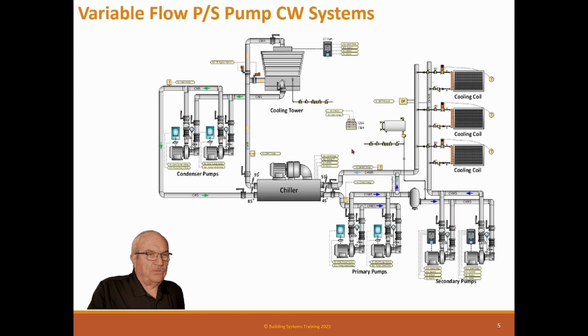Now, the controls for the system, we'll talk about that in a minute. We have starters on these pumps, and these are not variable flow. These are constant flow. And then we have VFDs over on these pumps because they have to speed up and slow down for these coils. And we normally have a VFD on the tower fan. It's a no-brainer to have a VFD on a tower fan.